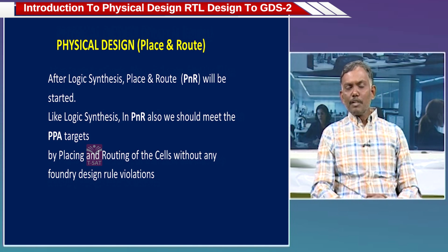But coming to physical design, the standard cell logic, whatever logic is present in your design, whatever IPs and SRAMs you have in your design, all should be placed and routed. Connections between those gates, between the RAMs and logic, must all be completed. That is called routing.